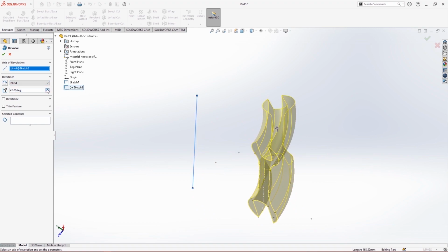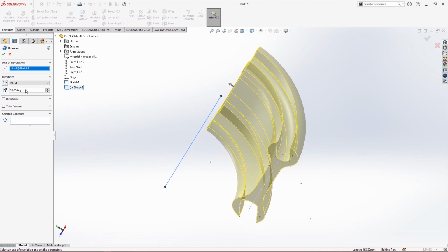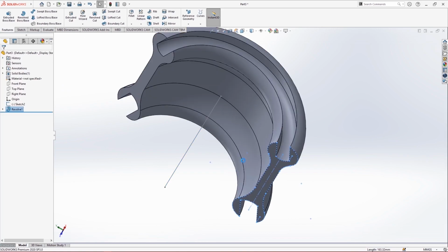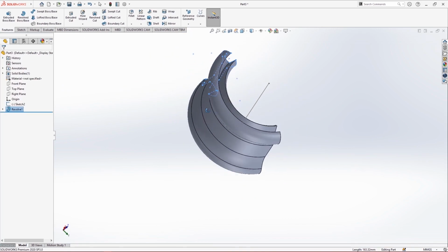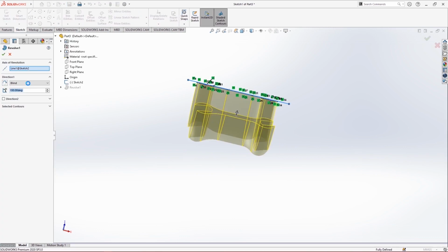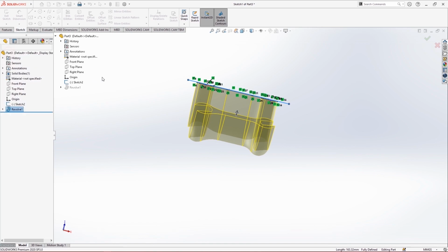You can see this is really beautiful. For example, I just want it to be like 150 degrees. I apply it, you can just exit, and you can see we are done here. It looks really cool. And other settings which are here include the direction, up to vertex, up to surface, and other stuff which I will cover in the exercise. So this is about the revolve. You select the contour and you select the axis of revolution, and you're done.